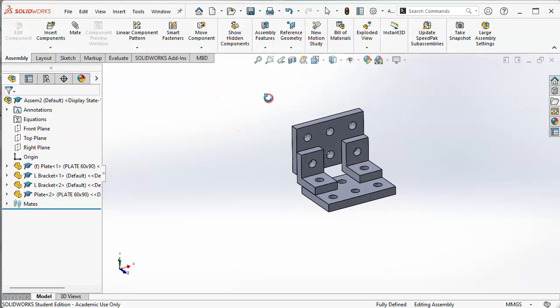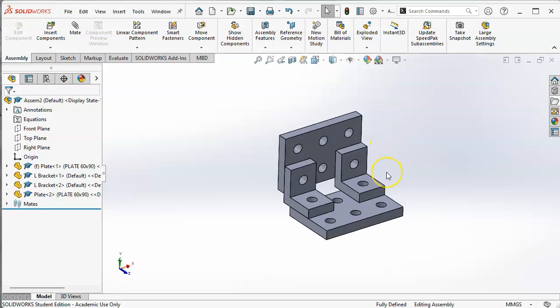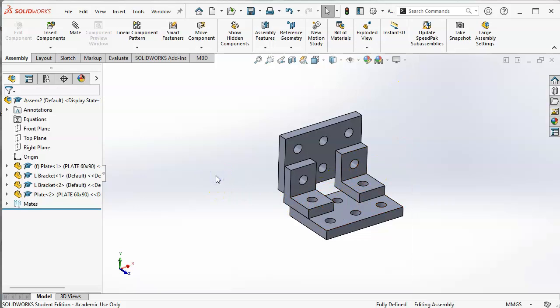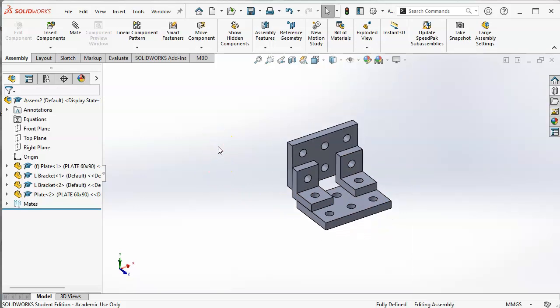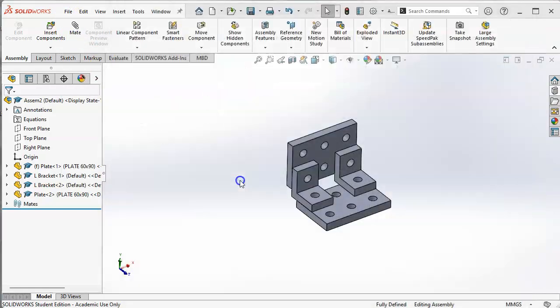All right, so eventually I'm going to do this to all of the parts, because if I'm reusing these and I'm doing this enough, there comes a point where the different combinations, depending on what our product is, what the design is going to do, but if I'm reusing a lot of these, I'm going to add the mate references, and then I'm also going to consider making a design library folder that I can just drag and drop these items rather than have them insert, and then they become kind of a global usable component. So what I want to do is open the peg.